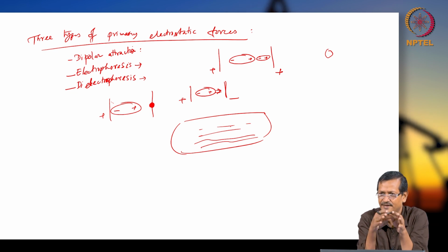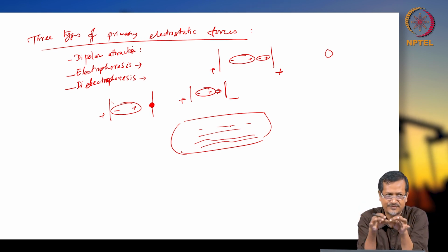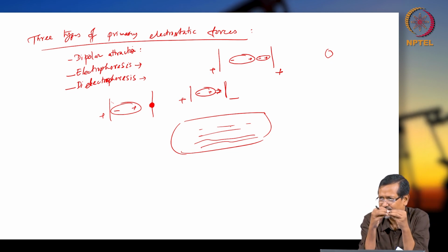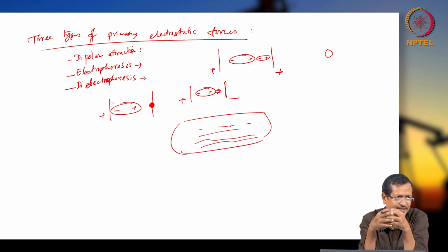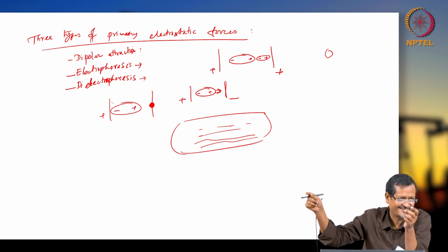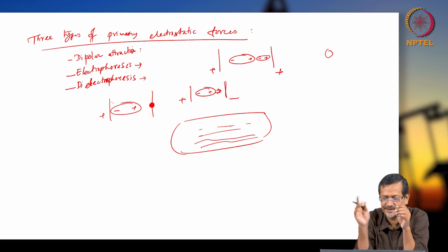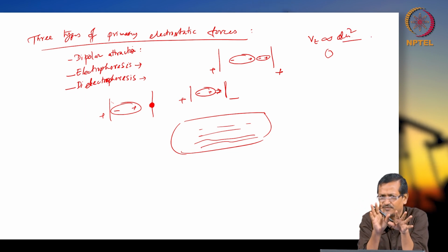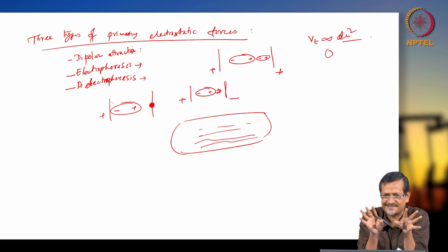If you have already removed the emulsifying part, fine. If something is still there, it is coating, and when the droplets collide, it is possible that they will fuse together and make a bigger particle. Vt is proportional to dm squared, just simple, you can remember that. So you are not changing oil viscosity or anything, you are just changing particle size.